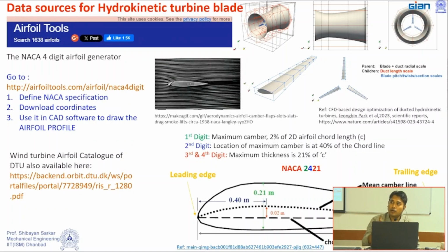Last day we discussed two types of engineering turbine. One is the drag force based turbine, another is the lift force based turbine. If we are talking about the drag force based turbine, its cross section will in general be rectangular. If it is a lift based turbine, you will find that the cross section has an aerofoil cross section. This is the aerofoil cross section.